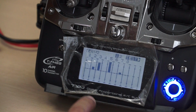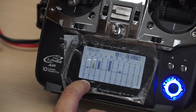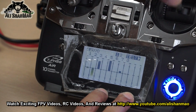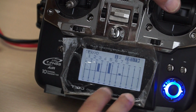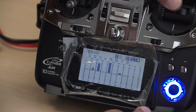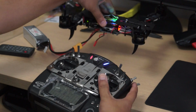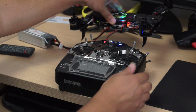Now if I turn off the mixing, this is the second mixing, you can see I have full 100% values on the elevator. So when I want to fly in manual Acro Plus modes, or like a traditional quad, I will be using the full values on the elevator channel. But when I want to benefit completely with the tilt rotor or dynamic rotor tilting, I will simply turn on the mixing and reduce the elevator effect, and let the quadcopter pick up the speed on rotor tilting rather than the whole quadcopter tilting.